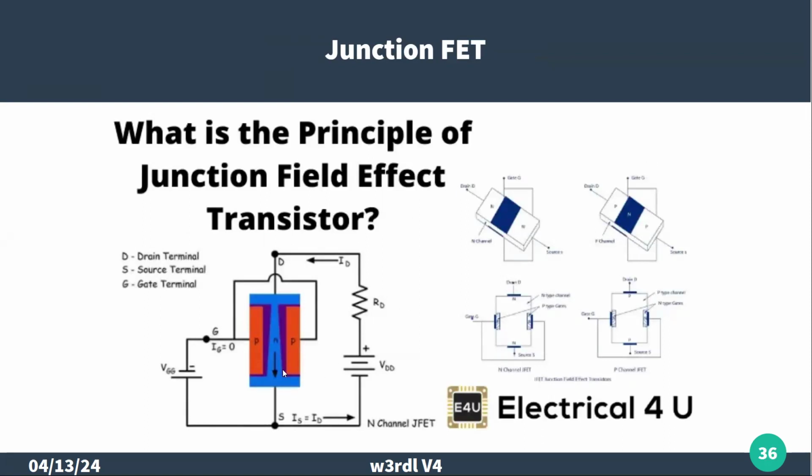Physically, this is a cross-section of what a junction field effect transistor would look like, where we have the basic N-type material and then some P-type on either side of it. And the center section, which is the gate, is connected internally. Here's the gate.